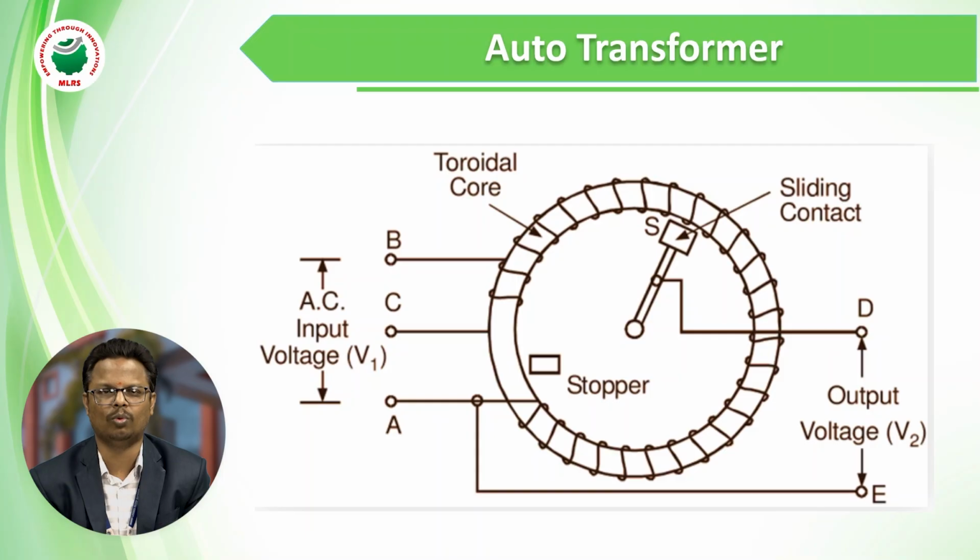Wherever we use a voltage control method to control the speed, we can use this auto transformer. And wherever the motor takes a high amount of current in starting, we can use the auto transformer. By slowly increasing the number of turns, the voltage increases, then the current increases slowly, so the starting current builds up gradually. By that we can protect the motors.